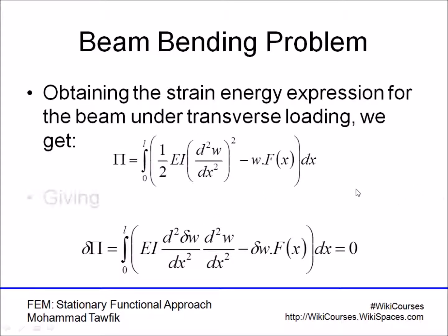So we end up again, like the last time, with d2w by dx2 all squared minus the deflection multiplied by the externally applied force, and this is the total energy.